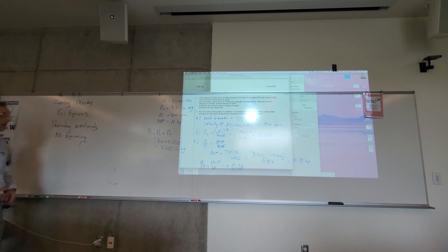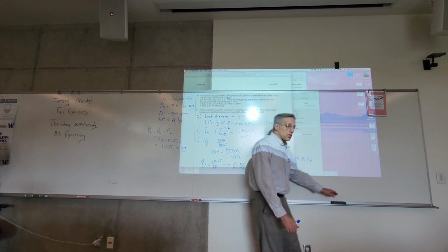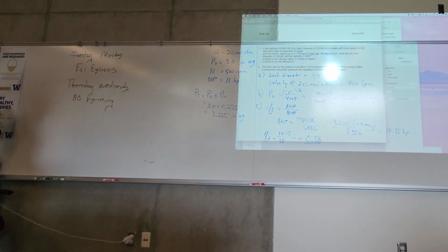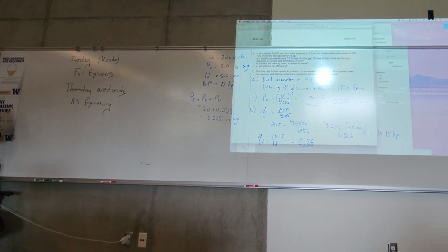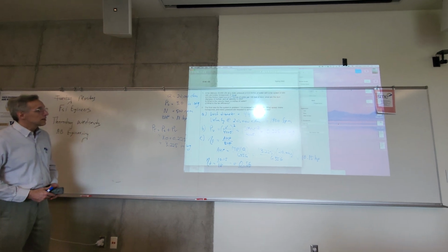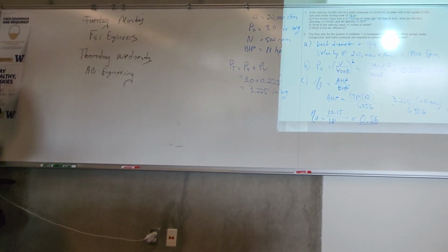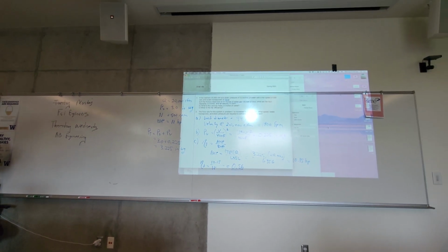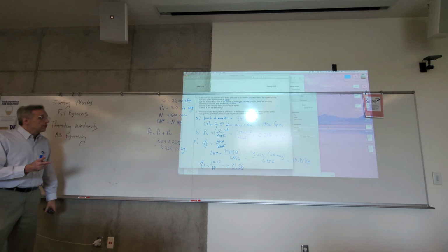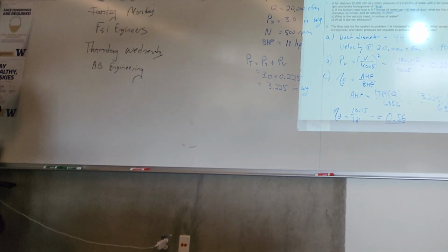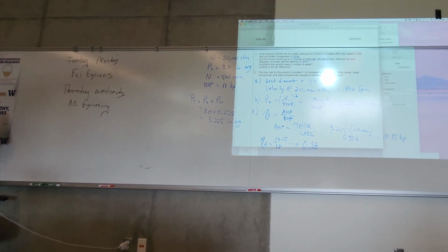Well, actually, we're going to have to make adjustments. We're going to have to alter the fan in some way to get 28,000 CFM. We'll probably increase the speed, but we could also increase the diameter of the fan. If the cage is big enough that we can put a larger diameter rotor, we might do that. But those are the 2 variables that we can usually vary without a whole lot of trouble. It's the impeller size and the speed of rotation.